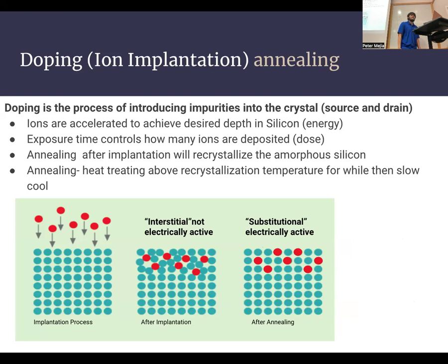It's interesting because depending on the amount of energy that you give these ions, it can change what happens to the material. Implantation is like the max energy. You just blast it, bombarding, so it goes into the material. But you could also give it less energy, and then it would be more like sputtering, so it could knock off material.